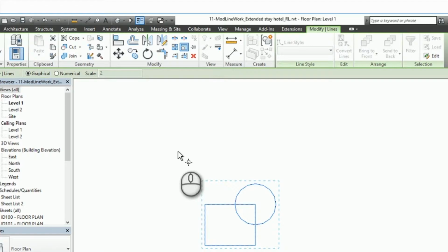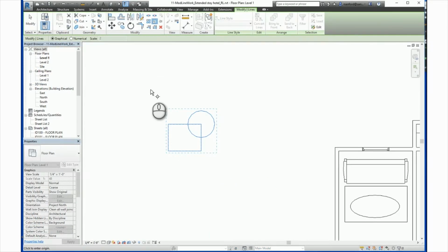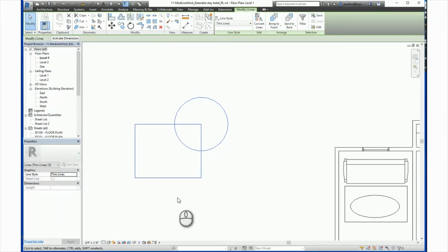And the first way to scale is we're going to do a graphic representation of the scale. So to do that, after selecting the elements, we'll click the origin of the scale, the original size, and then the third point, which will be, let's say, the scale size of the elements. Now we'll hit Control Z to undo that.